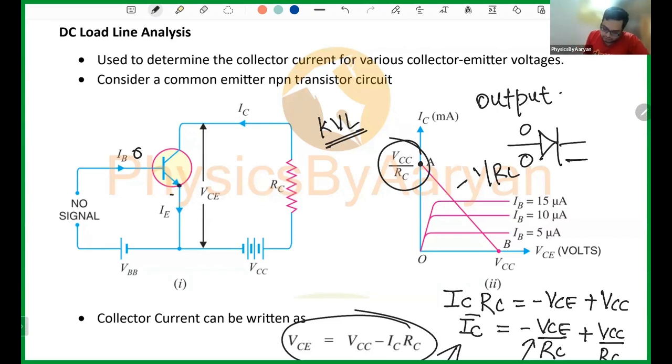This thing is negative, this thing is positive, and this thing is 0. So this is at higher potential, this is at lower potential. So this is exactly what you want, and this is forward biased. For this thing, this is at lower and this is at higher, so this is reverse biased. Exactly what we want. Why will it be in reverse, saturated or any cutoff or anything of that sort? So your transistor is properly working, no problem at all. This loop is still closed. Even if your input signal is not there, this thing is closed.